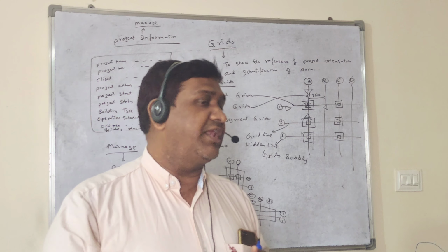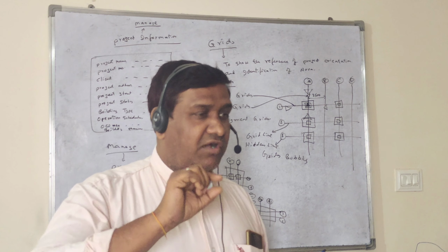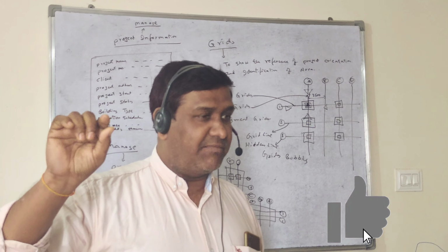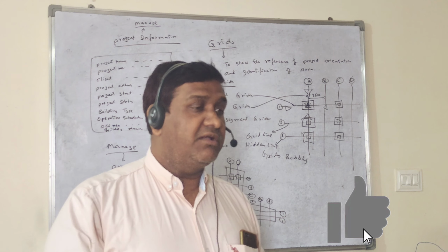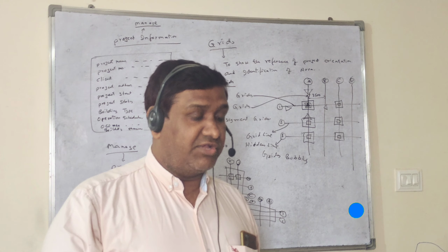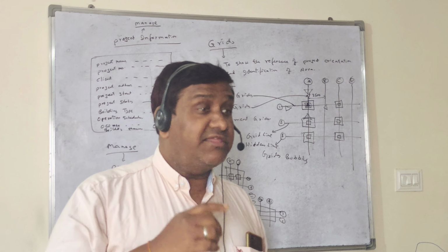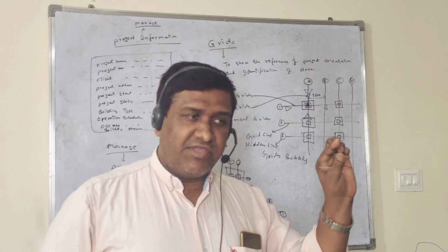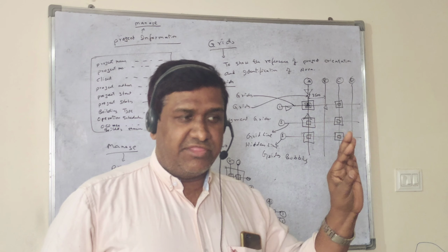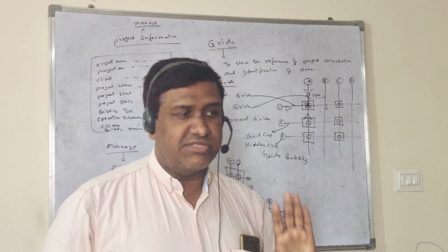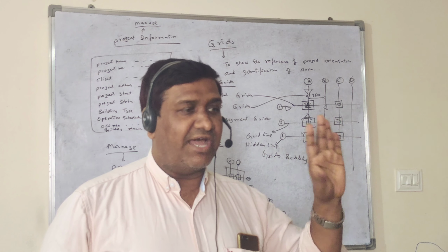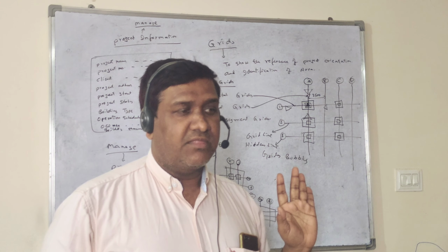In AutoCAD we do it like that. Because in AutoCAD, if you have given the dimension in mm, it will never change. Again you have to prepare it with meter or some other unit which you require. But here it is not like that, because once you have given the dimension a unit, whichever unit you require, you just go to project units and change the unit, that's all. Automatically the value is also going to change.